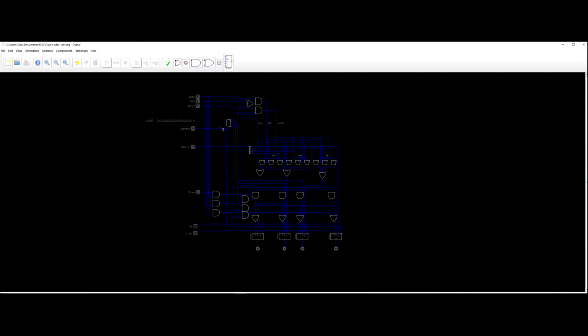Oh yeah, I use Digital all the time. I like block design. I don't like writing code. I don't like having to visualize how code flows. I like being able to look and test my circuit in something like this, and then it literally just exports VHDL. Not only that, but Digital is natively compatible with the CPLDs that I'm using at work, which are literally the latest greatest CPLDs on the market, the ATF15XX series. So you can get them from the 1502s all the way up to 1508s. There's 1504s, 1506, 1508.